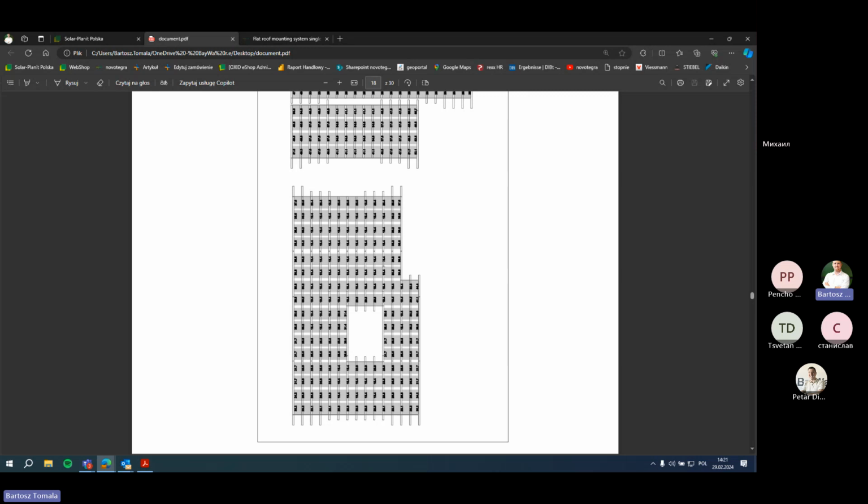And if you want, we can recalculate the whole construction to be without any ballast, only on these welding plates or something else, because it doesn't always have to be with welding plates. It can be made also with anchors or something which you want to use. We only have to know from you what the pulling force of this point will be, and our static engineer will tell you how many points and where you have to put them to make it safe, of course.